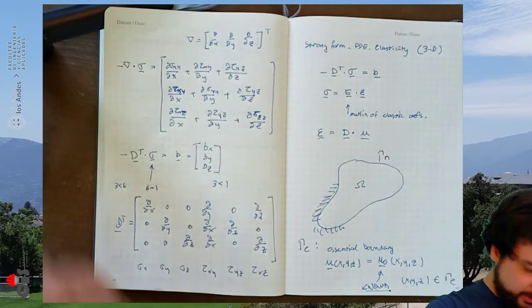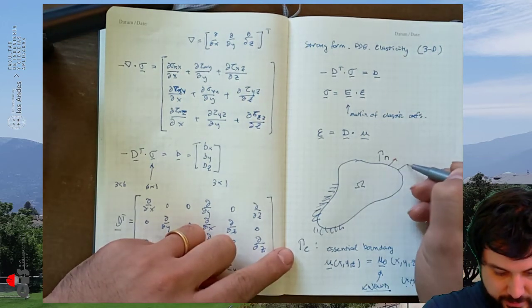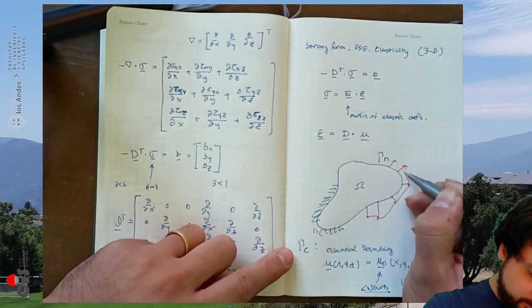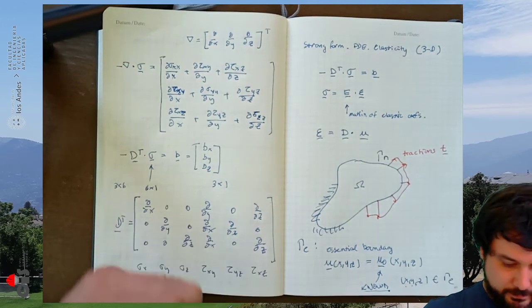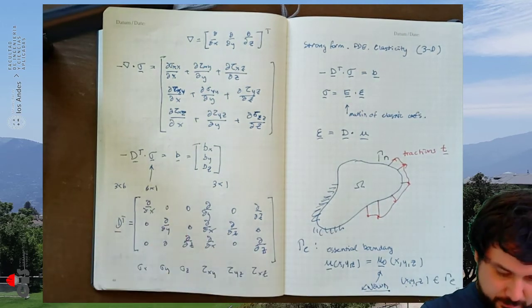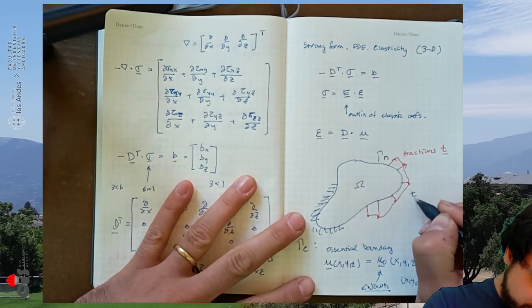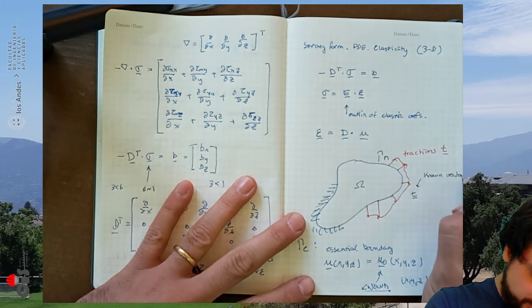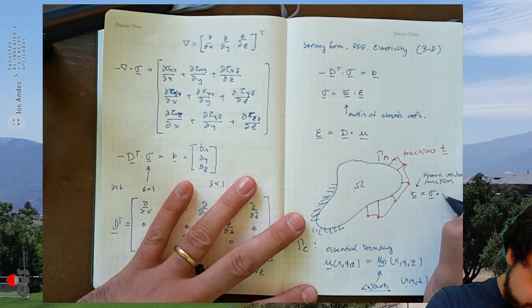So those natural boundary conditions might be applied forces, applied tensions, for example, applied so-called tractions. So we have some tractions, T, and the way it works in the equations, the traction is a known vector function equal to the stress tensor times the normal.